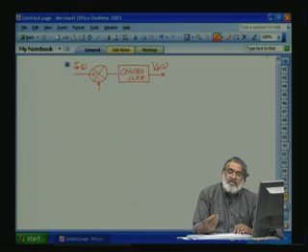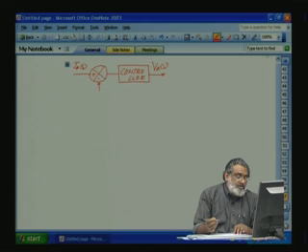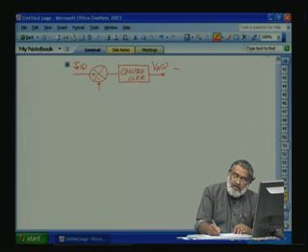We have to control the armature voltage in such a way, as I told before, for fast dynamics, the machine should always be drawing the maximum current, maximum positive torque and maximum negative torque, depending on the current rating of the machine. So VAS, the applied armature voltage, should be based on the current controller.